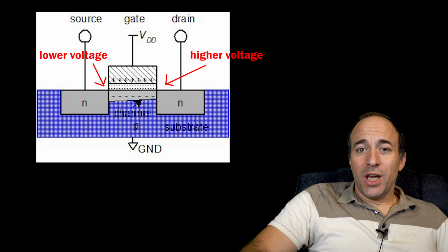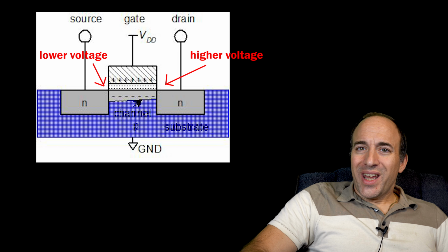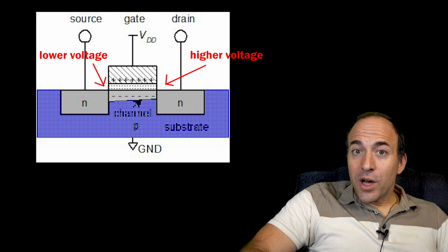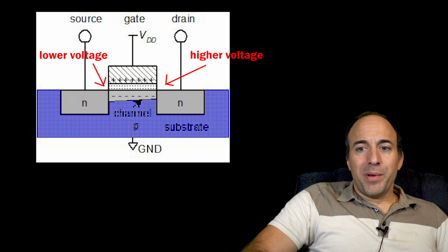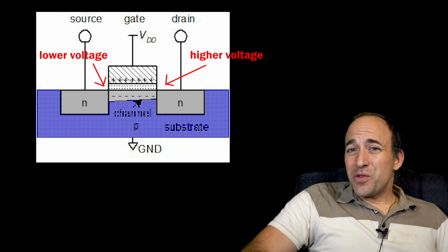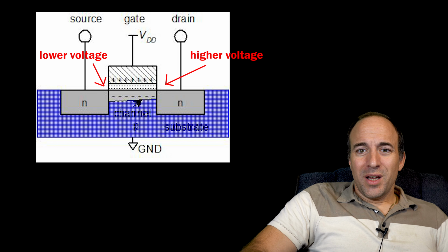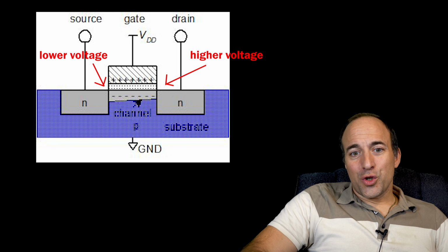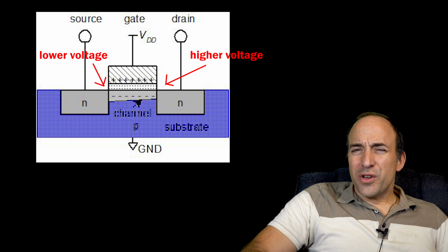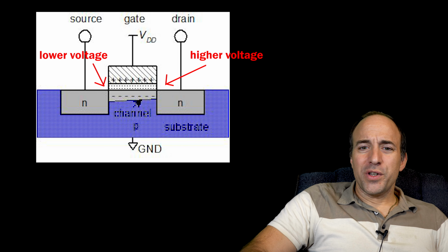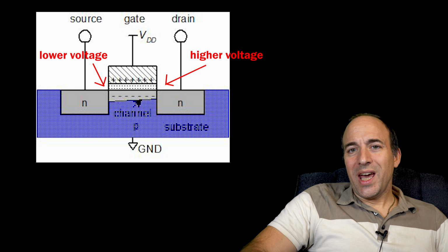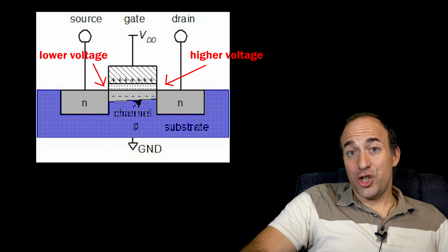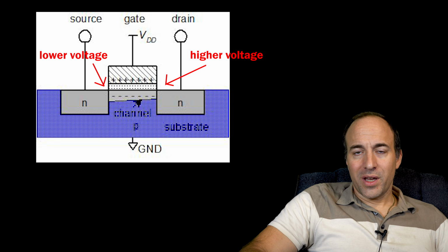So ideally, you want each side of an N-type transistor, when it's on, to be connected to voltages close to ground. Because otherwise, the higher voltage of the source and/or drain will close the voltage gap with the gate. In other words, the gate voltage is relative to the channel because of the capacitor effect.